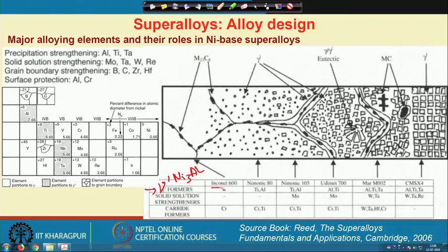In Inconel 600 or the Monel series, we do not add this, whereas the microstructure mostly contains precipitates at the grain boundaries, which are M23C6. These are carbides, and they form during hardening, or any treatment, or during service itself, and strengthen the alloy, where the carbide former chromium is required, replacing the M here.